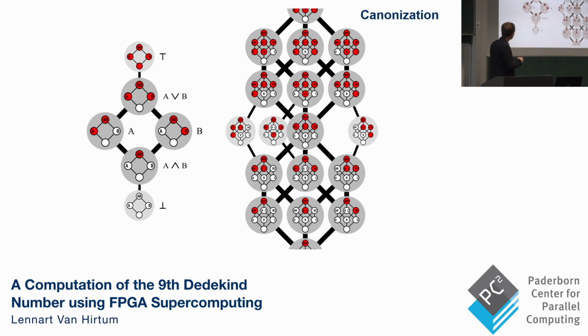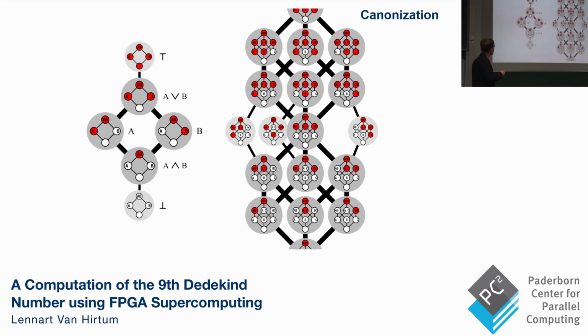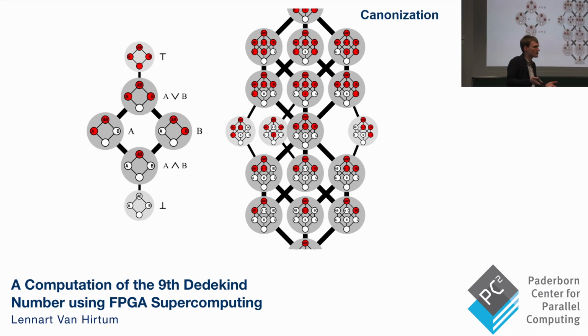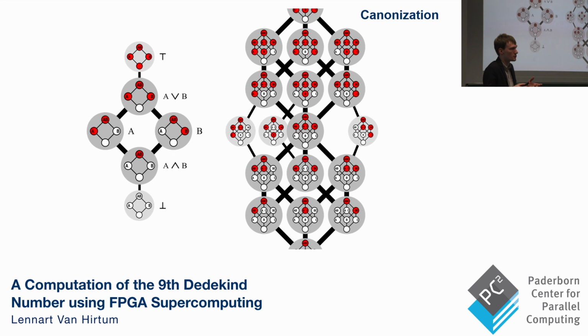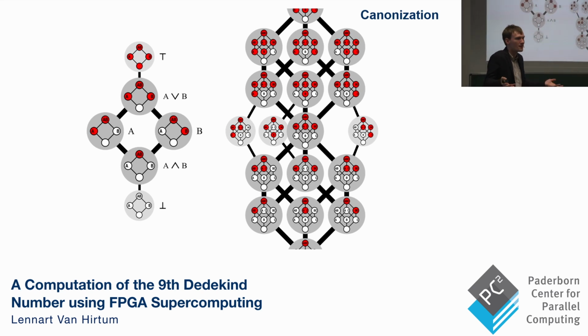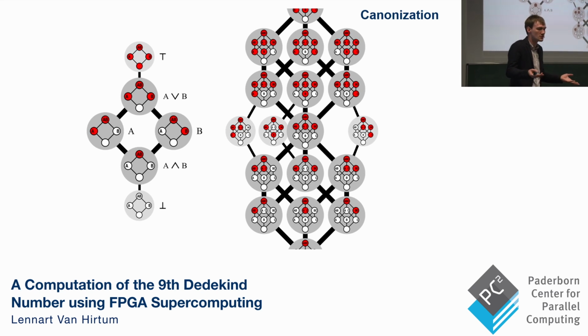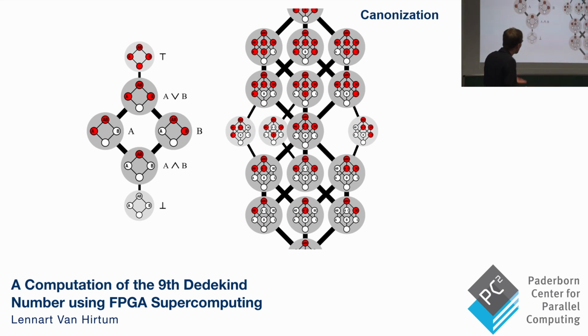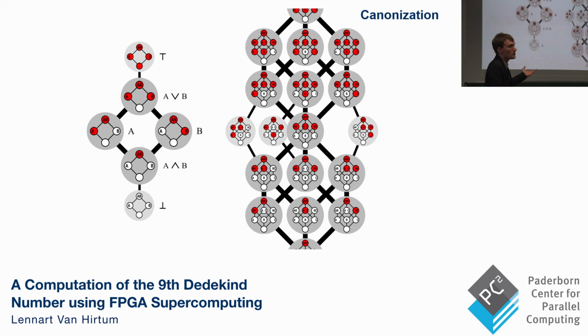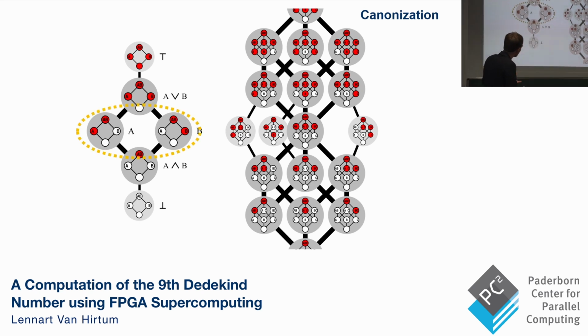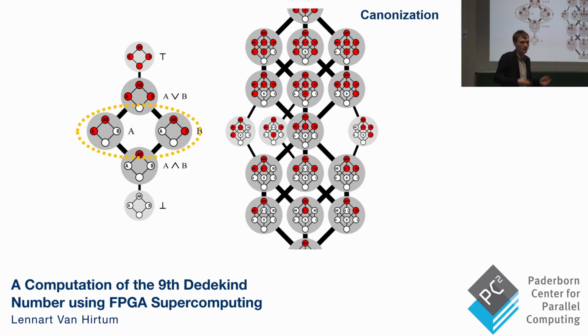This A Boolean function and this B Boolean function have the same structure, they're kind of rotations of each other, or swaps of the variables. We don't particularly care about the naming of the variables. So we could just treat these two as one Boolean function, and group them in one thing we call an equivalence class. This is an equivalence class which has size 2. In 3 dimensions, it goes even further.